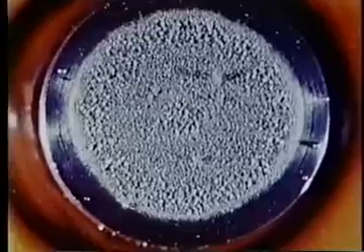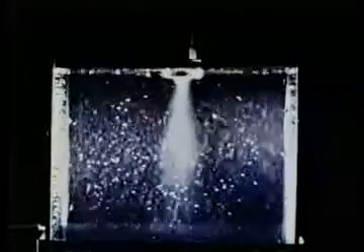After 1 minute, the highly polished surface has been eroded, and significant weight loss has already occurred. Here is a side view of this experiment. The high collapse pressures and the mixing caused by ultrasonic cavitation is put to good use in industry. For example, for accelerating chemical reactions, industrial cleaning, and homogenization of milk.